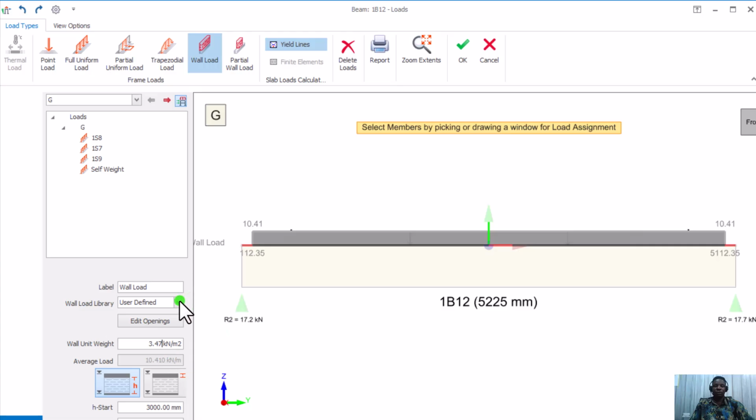Look at what we do here. They use these 200 bricks to calculate it, so that's why they have 2.4 initially. But now we're changing it to the 9-inch block, which is 2.87. So we're adding the partition width, which is 0.3 plus 0.3 at both sides. So we are doing 2.87 plus 0.3 plus 0.3. This is how we came about this value here.